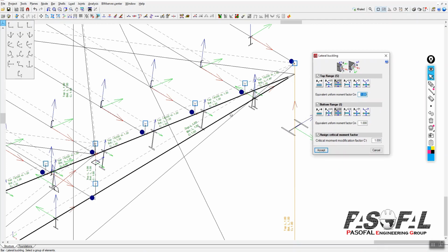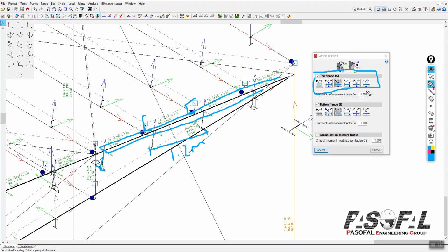If you are working with beams, it's easy. For example, if you are working with the rafter, it's easy because you know that here it is the rafter, as you can see, and at the top of the rafter you have the purlins. Okay, so here if the rafters just continue like this, at the top of the rafter we have the purlins. So simply you can come to top flange. Okay, and then you can just measure the space between the purlins, for example 1.2 meter, and then simply here you can again go to effective length.